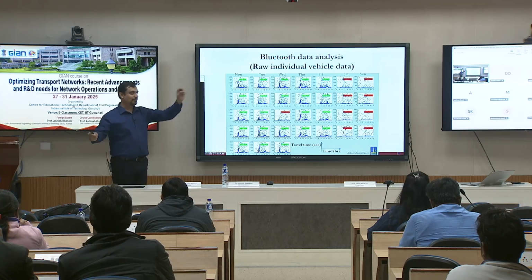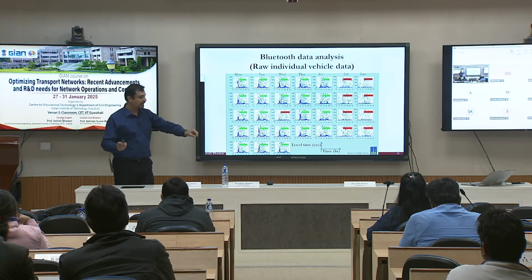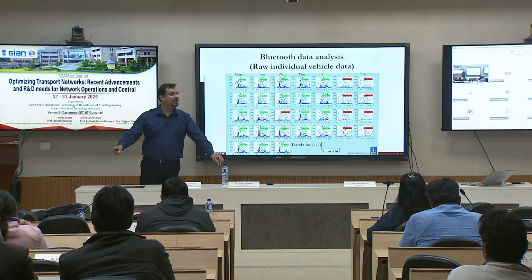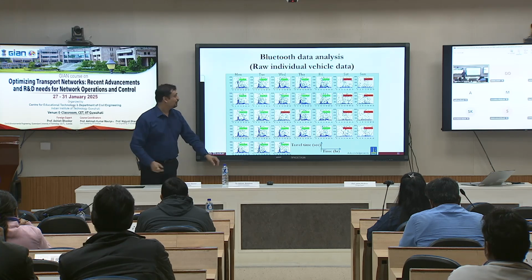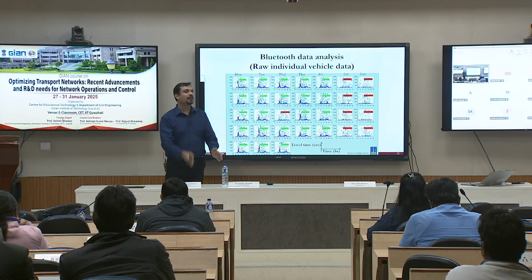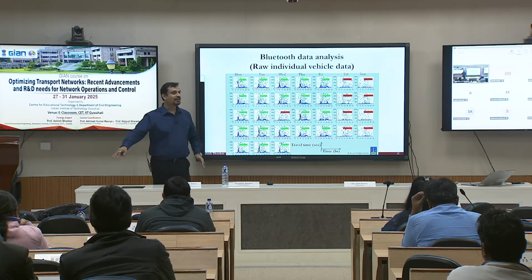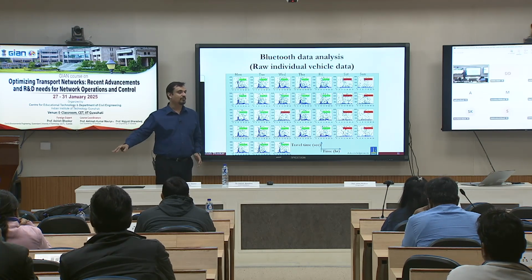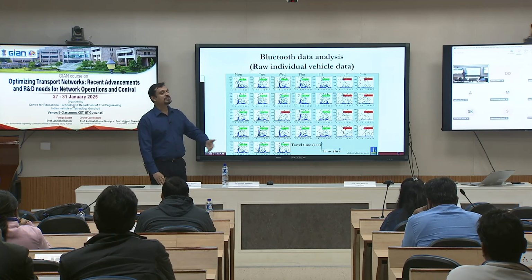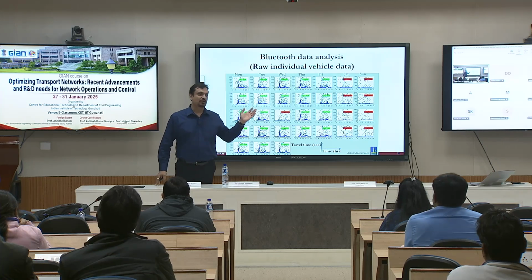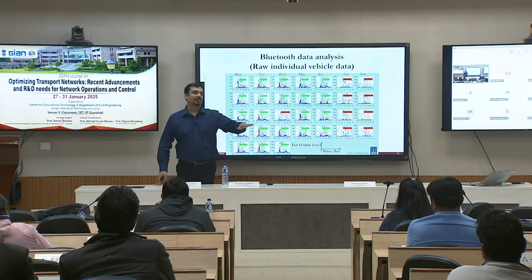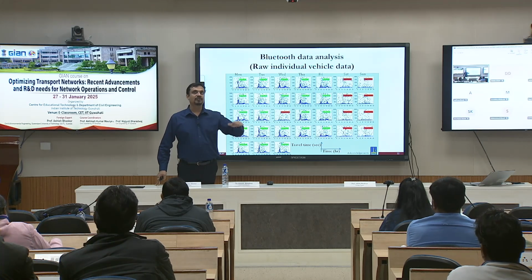So if you do your matching like that, you can have an observation of maybe 18 hours. But you do not want that, so you say I'm going to cut it off after a certain value, because I don't expect that it will have such a bad travel time. One way to do it is to assume a speed of, let's say, 5 kilometers per hour for the corridor and make a cut. Those are the heuristics you have to add in your algorithm.